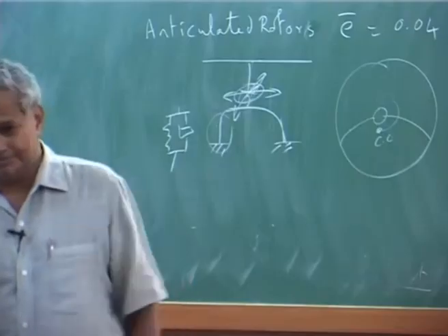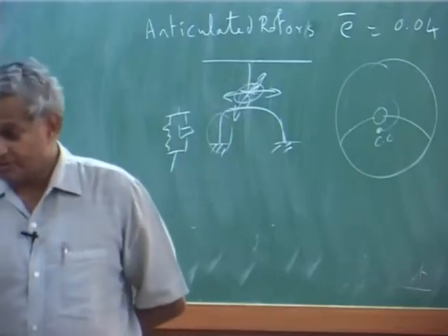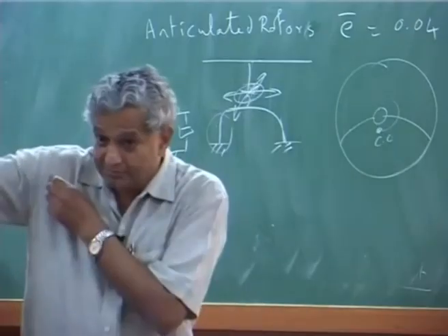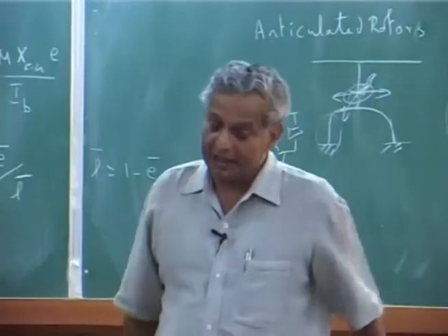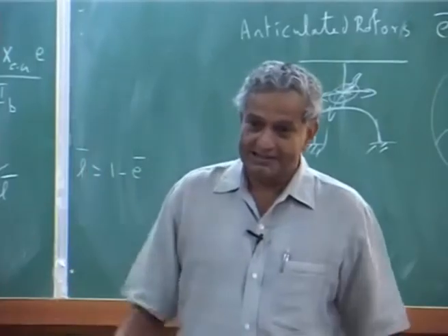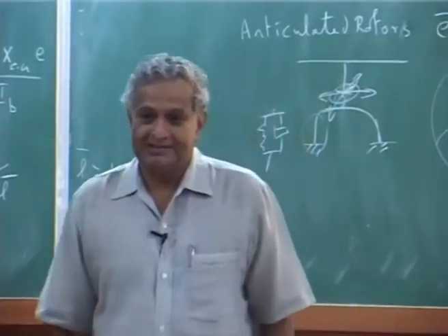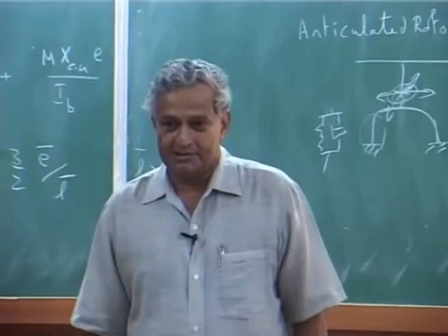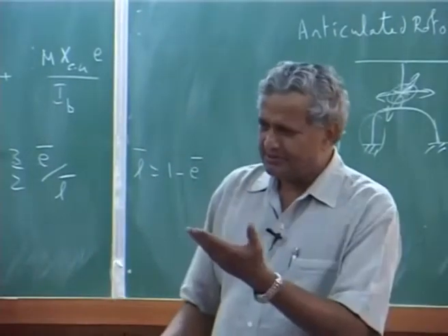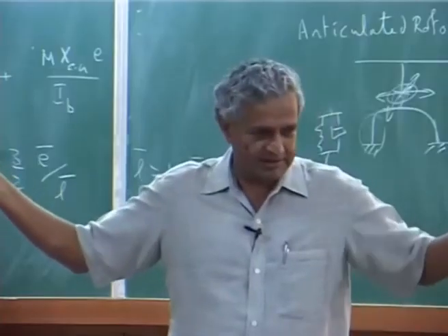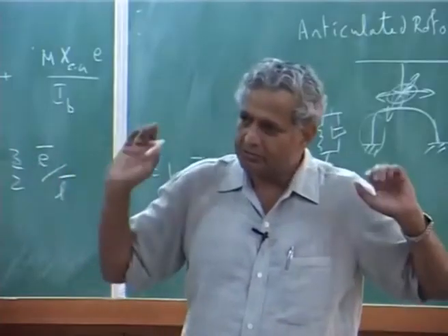You may put a damper then in that case, because your tail boom with the lead lag can get into, yeah, you will get into that instability, okay, because that is like a ground resonance. The support structure, that is what happened in the tilt rotor, what he was showing that day, the amount of problem they see.